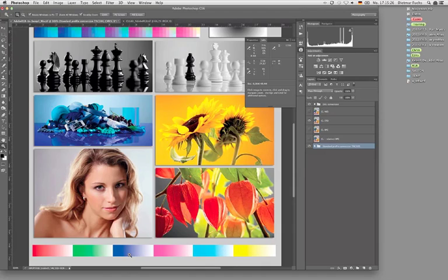So you get a real cyan, if you like. You get a more saturated magenta. You get much higher saturated reds. If I'm switching now between the normal ICC conversion and the DeviceLink conversion, you'll see much cleaner colors here. That's one of the beauties of the DeviceLink, where you can target the conversion to give you much higher saturation, much cleaner colors. I would like to show you how to create those DeviceLink profiles in CoPra.